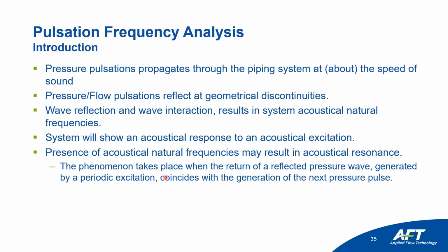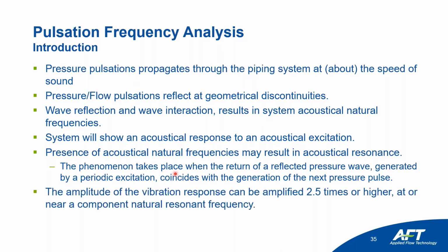The phenomenon takes place when the return of a reflected pressure wave generated by periodic excitation coincides with the generation of the next pressure pulse. The amplitude of the vibration response can be amplified 2.5 times or higher at a near component natural resonant frequency. So if you're operating near an acoustical natural frequency, you will have acoustical resonance, and consequently, you will probably have high displacements on your pipe.